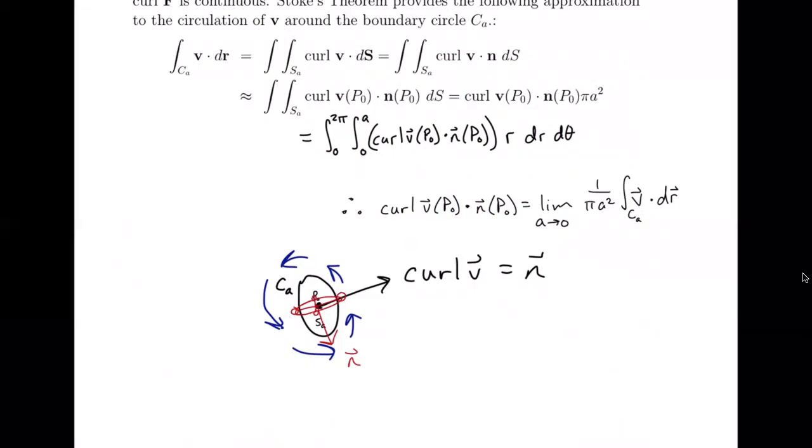Well, it's not going to turn anymore. The fluid flow is traveling orthogonal to each of these little paddle arms, and it won't spin it in any way. So in this case, our circulation would be 0, and that is exactly what this says on this side, and it tells us that that circulation integral would be 0.